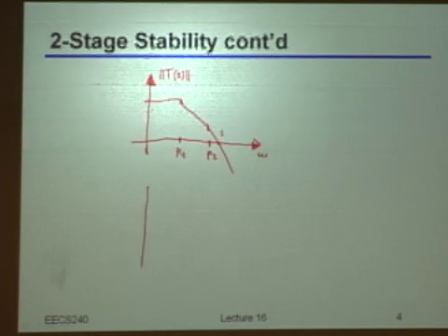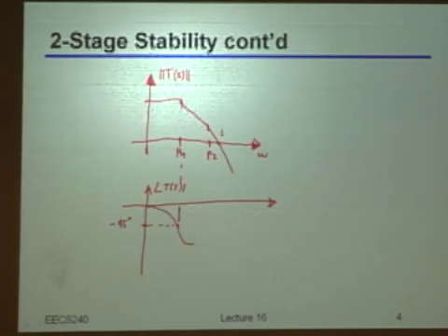And on the phase plot, we will have the angle, again, of T of S. At this point, the phase plot wouldn't be so steep as in the past. I will have here just minus 45 degrees phase shift, and then we'll get to minus 90.